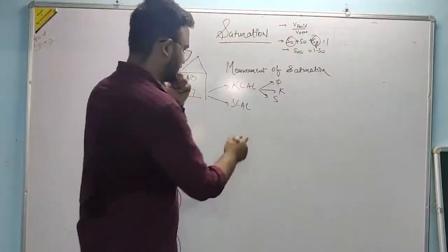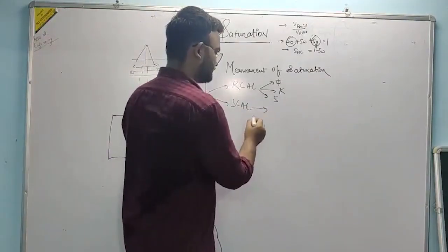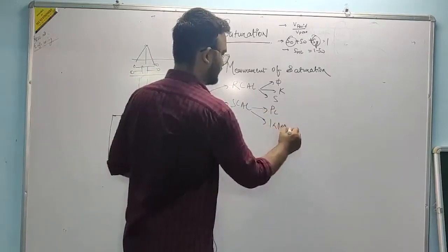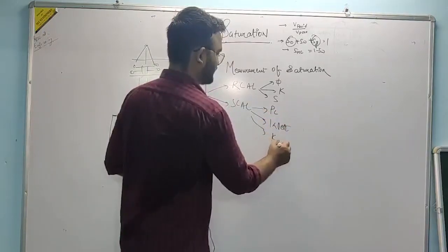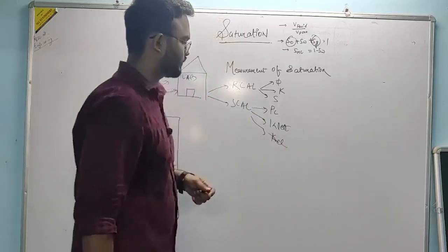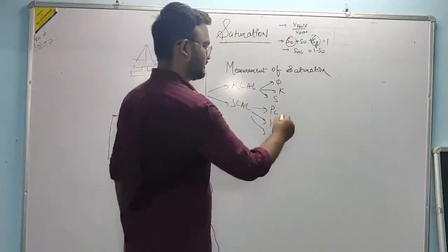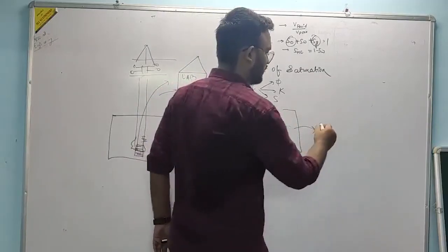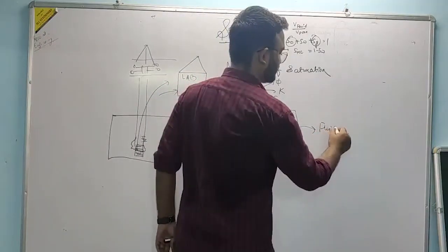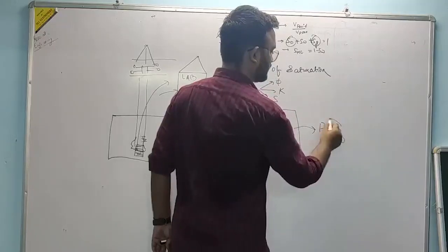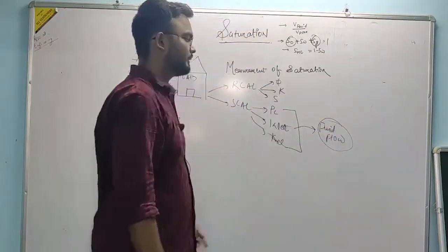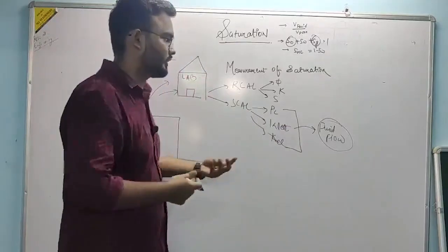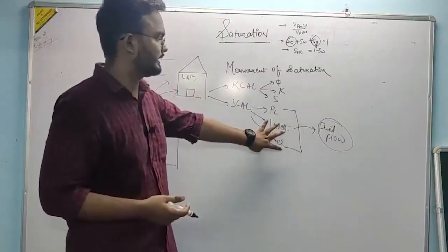And in SCAL properties, we measure our capillary pressure, wettability, relative permeability, etc. These things are basically deciding how fluid flow will be taking place. They decide how interactions are taking place, how rock is behaving along with fluids. These are the detailed part.